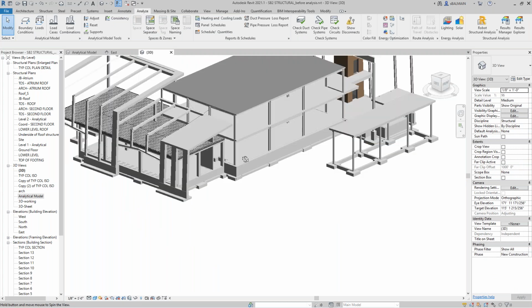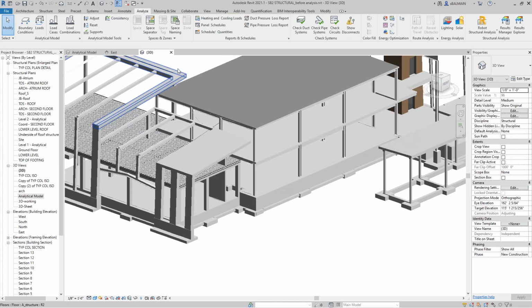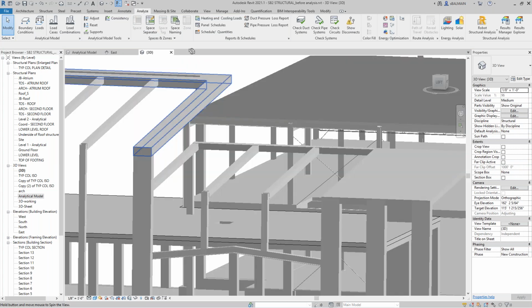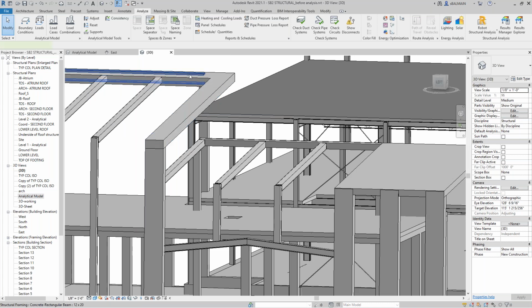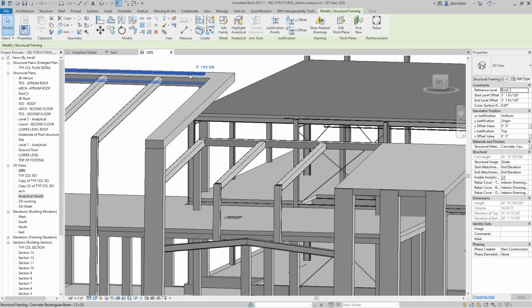You see here? Yeah, that's what I mean exactly. When you are talking about, for example, a slab in Revit, it is represented with the thickness as well. And in Robot it is only a plane without thickness in the model. So it's a rigid link or something like that. So yes, I wonder how to handle this between Revit and Robot.